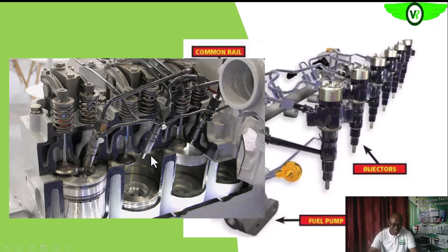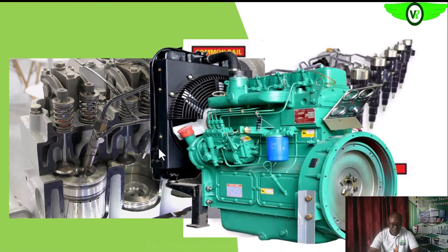Okay, we have two valves here. One is the intake and the other is the discharge valve. These are the rocker arms that we discussed earlier. So you see that as the push rod pushes the rocker arm up, that will depress this spring, okay, as it is pushing on the valve to open. Are we getting it? So the spring at that point will have been compressed. So when the camshaft lobe has moved away from the follower that pushes that push rod, as we saw earlier, you'll see that the force on the rocker arm will have been relieved. Okay, so once it's relieved, this compressed spring will release, and then the valve will return back to its closed position. So that is how, like we said, we have both the exhaust and the intake valves.